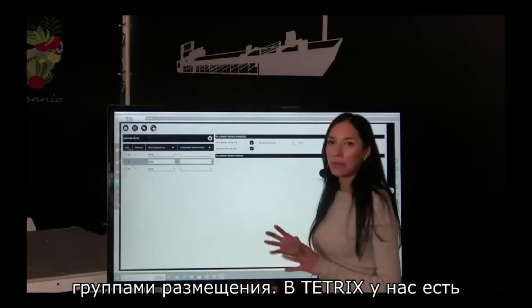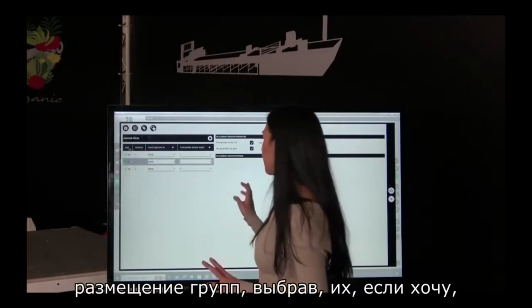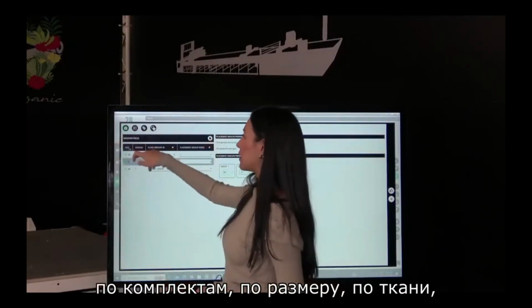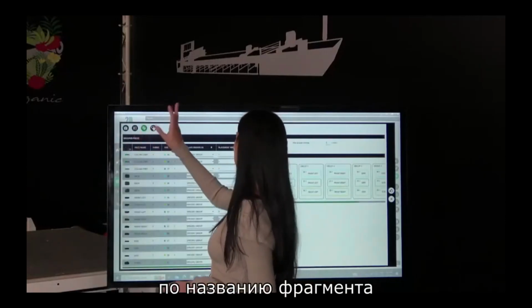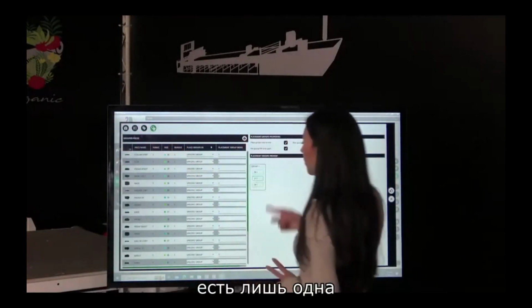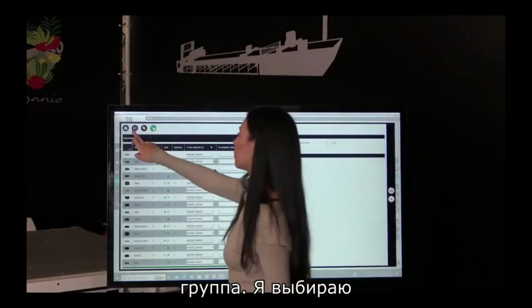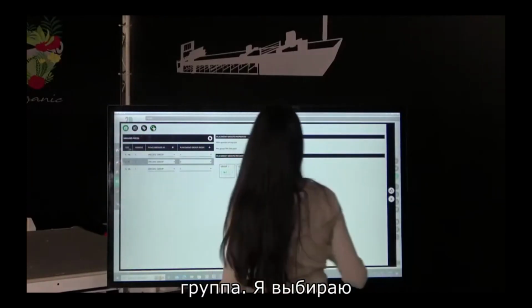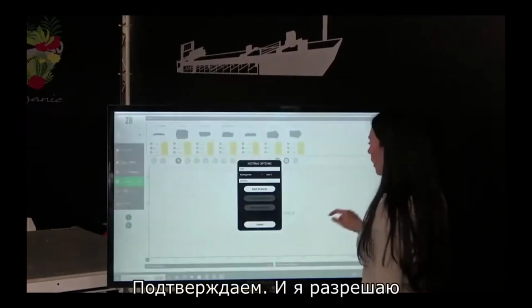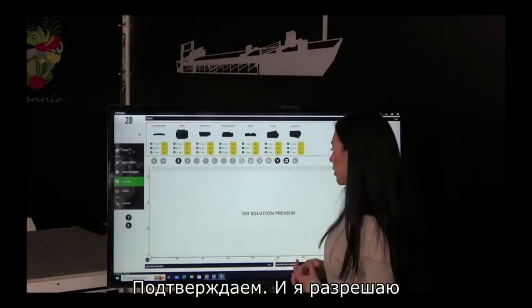With Tetrix, we have the possibility to create automatic placement groups by selecting if I want them by bundle, by size, by fabric, by piece name, or by fabric type. In this case, we only have one, so it's going to only be one group. I'm going to select by bundle, confirm, and I'm going to allow it to nest for a second.